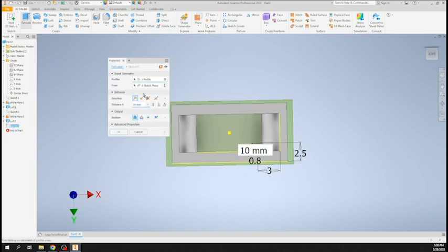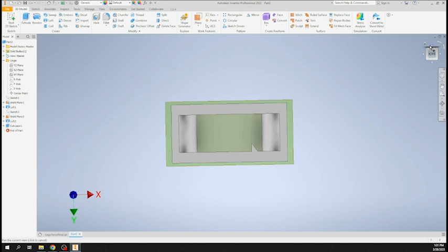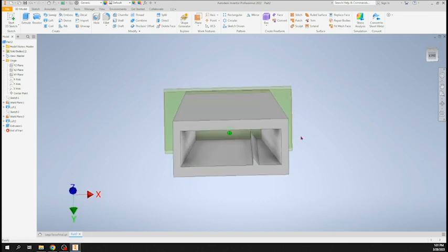And now we're going to extrude that. We're going to use a feature we haven't really used too much. Maybe you have if you use Inventor a lot. It's called To Next. It's right here. Make sure you click To Next, and you have that triangle selected, and go ahead and hit OK. What does To Next do? It extrudes the object all the way to the next object. So it went all the way to the top. That's what we wanted.